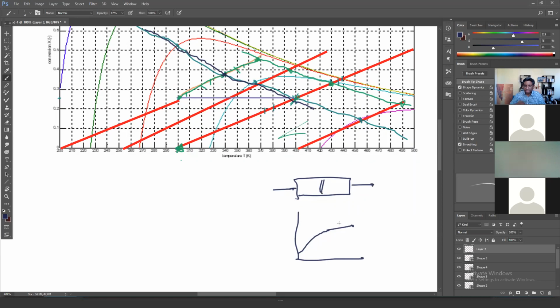So if you chose to stop at that endpoint, it's almost like saying, just when it gets good, it's over, right? You'd be positioning your best possible reaction rate right at the end. You don't want your best reaction rate right at the end. You want to move that to be the average operation in your PFR. You'd rather have a situation like this instead.